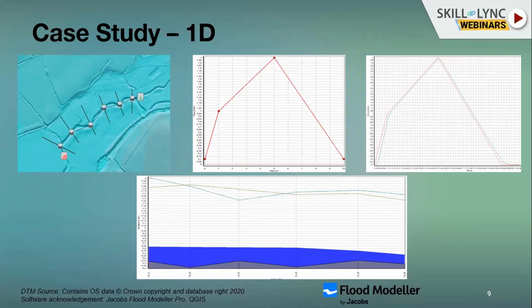While building any model, people should be aware that there are five parameters, or five boxes, I'll say. First is the general parameters: what's the temperature, what is the specific gravity that you'll be using in the model. Second is your geometry, which is equivalent to your DTM or ground model, or the roughness.